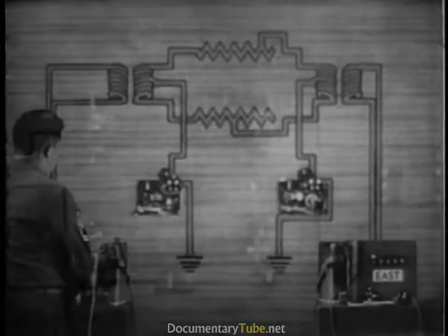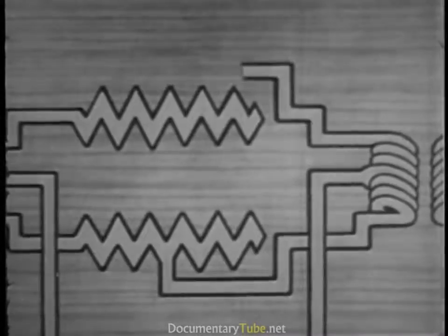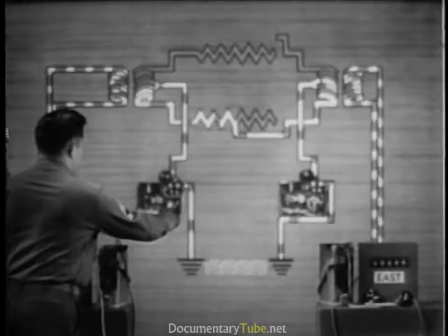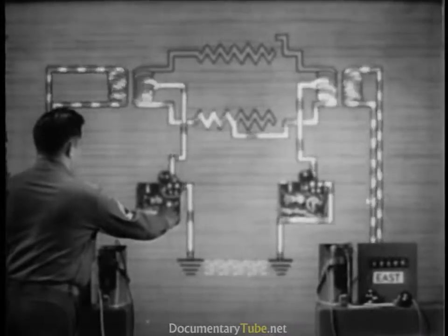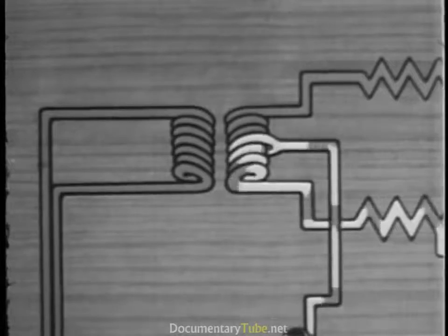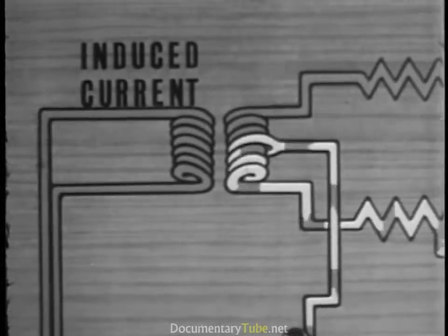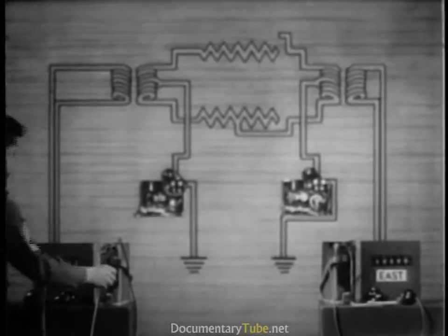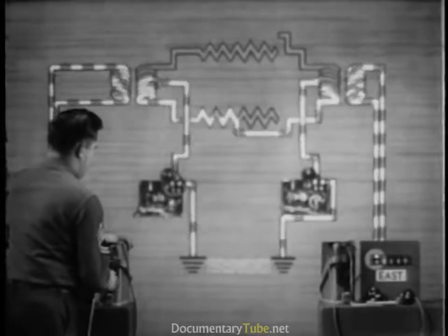The extreme condition of this unbalance occurs when one line wire is open. Now, all the telegraph current travels over one wire. And the current induced in the telephone circuit is at a maximum. Telephone signaling is usually still possible, even with the open line wire.